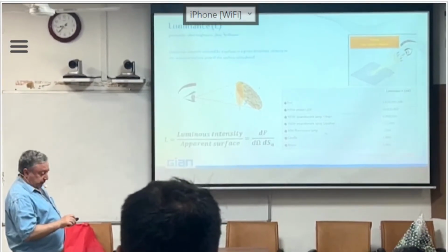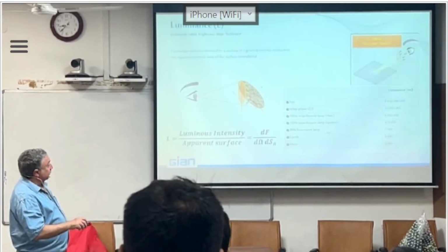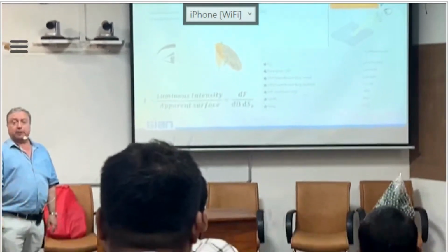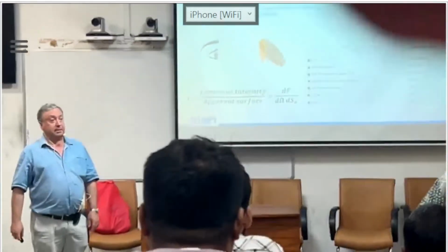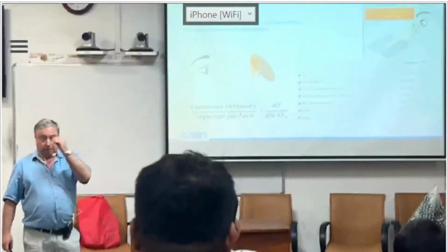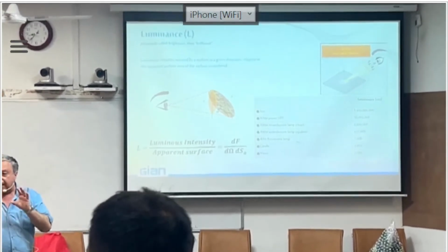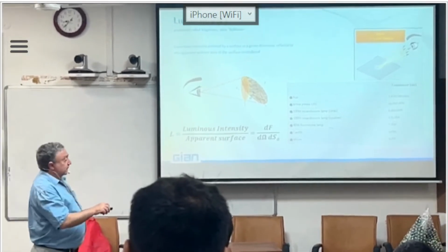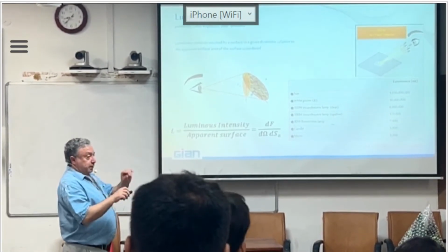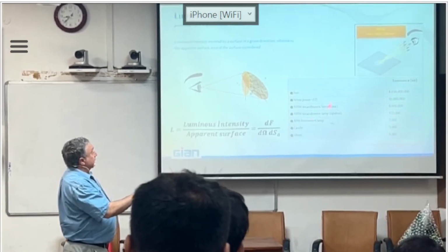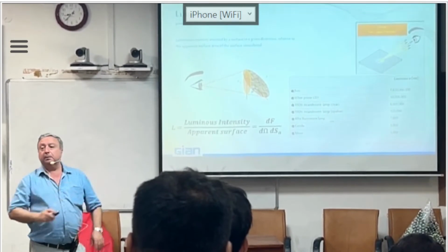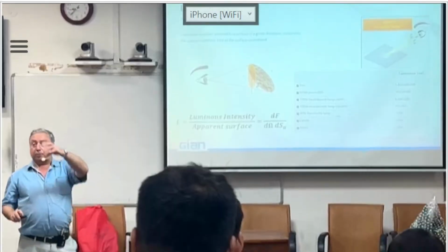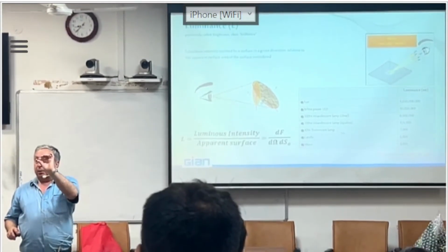A white power LED: 10 million nits, 1,000 times less bright than the sun. When you see a small LED in front of your eye, if you don't diffuse it, you will be glared. An old clear incandescent lamp, where you can see the filament: 6 million. The same incandescent lamp with an opaline bulb: 125,000, because the emitting surface is the full bulb, not only the small filament.